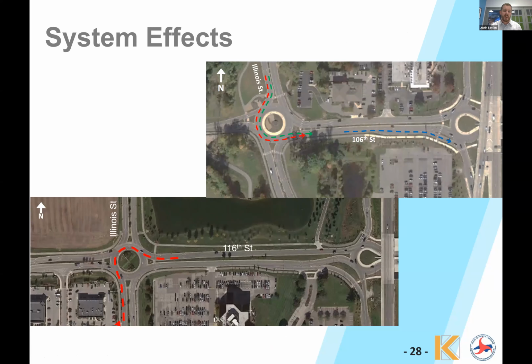So at the one that's performing better, 116th and Illinois Street, the crashes that are occurring seem to be directly related to the destination that vehicles are trying to go to. We're seeing high numbers of vehicles for the southbound right turn movement shown in red and green that, instead of being in the inside lane to make a left turn, which is the green arrows, are actually staying in the outside lane, that red arrow, because immediately downstream they're trying to get to a freeway on-ramp.